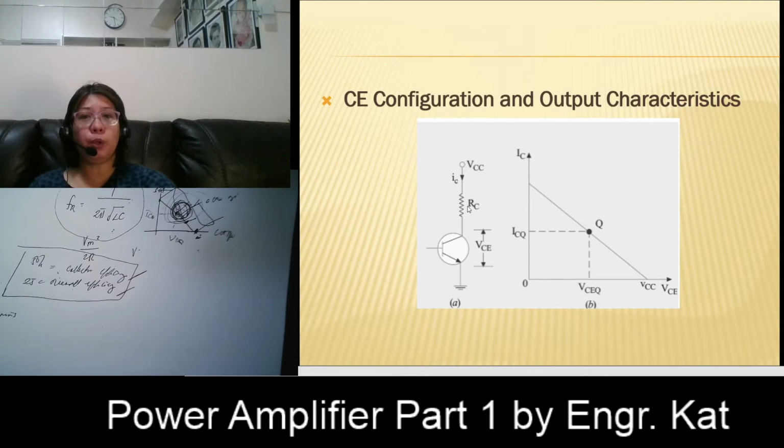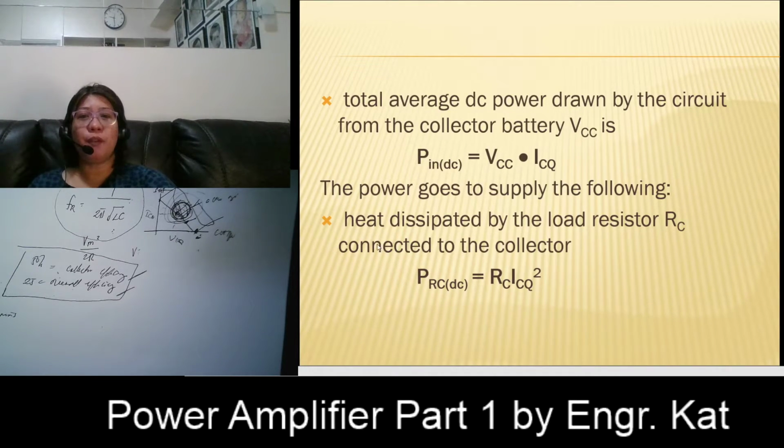As you all know, resistors don't have only resistance, but they also have a power rating. There are resistors having 2 watts, 1.5 watts, 1 watt, or even 1/4 watts. It is the value of how much power they can dissipate. For example, in a real circuit, when you touch this resistor, you can feel it is hot. Why? Because it dissipated power already. Current flowing across this resistance produces power, and that is in the form of heat.